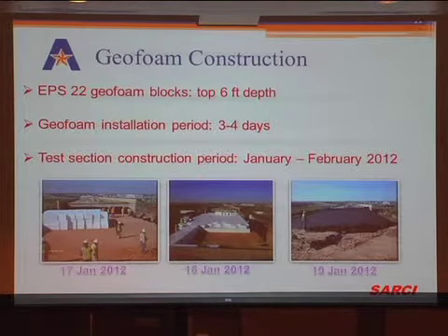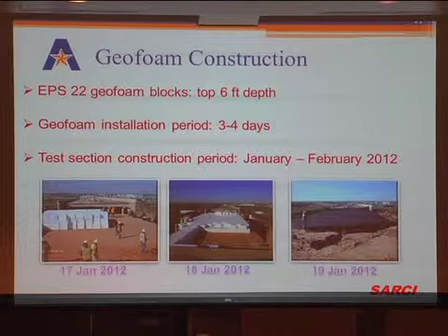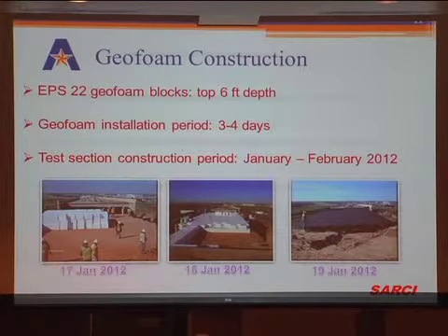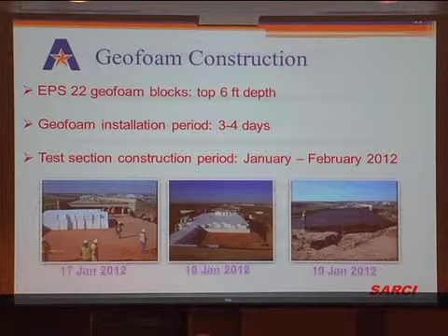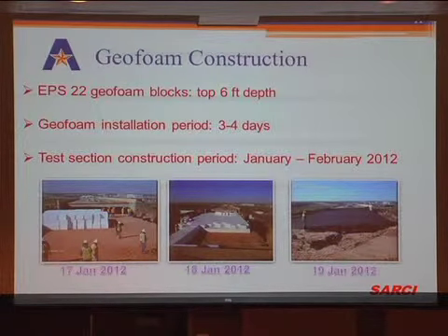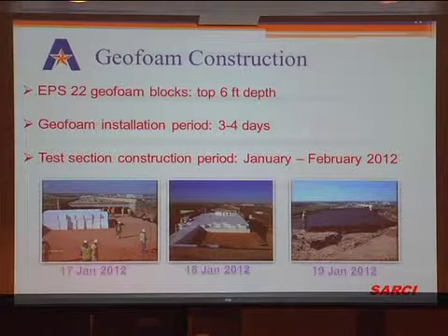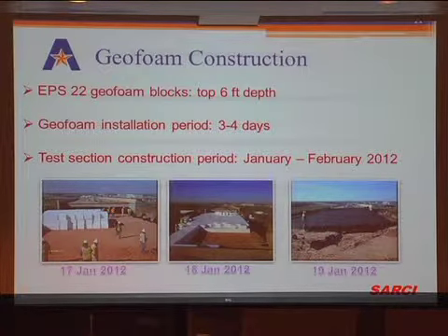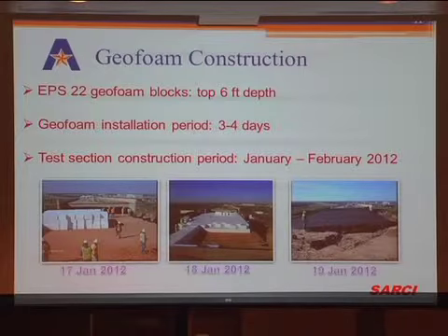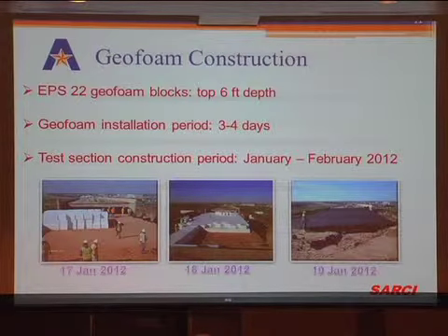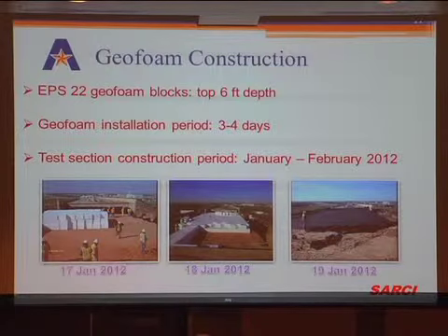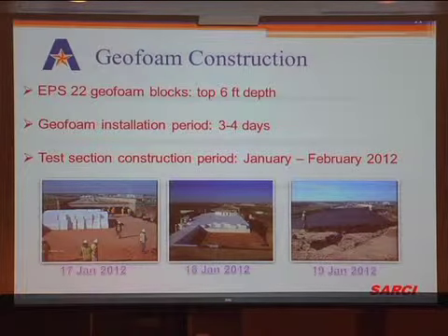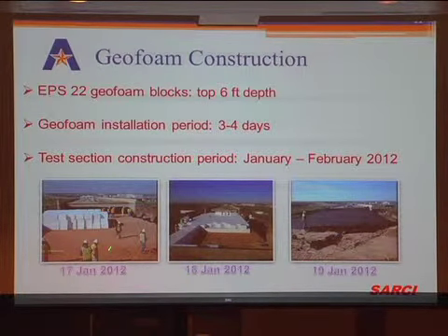And when we finally convinced them that this is a good approach, the way we did it is we didn't ask them to remove the whole 40 feet of embankment, and this particular embankment is 40 feet. We know that's going to be very expensive. So we said, let's try something unique, a hybrid type. Leave some part of your embankment and put in about one third, maybe a height of 6 to 7 feet, of foam material. In this particular case, we put 6 feet on top of this one.